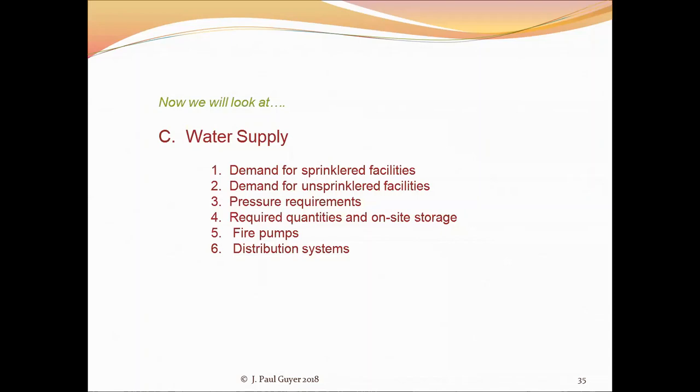Conceptually, you're building barriers, walls, ceilings, floors to prevent the spread of the fire to other parts of the building, and maintaining the integrity of the egress routes, the corridors, the stairwells, is very important, because those are the egress routes people use to get out of the building, and they are the access routes that the firefighters use when they show up to fight the fire.